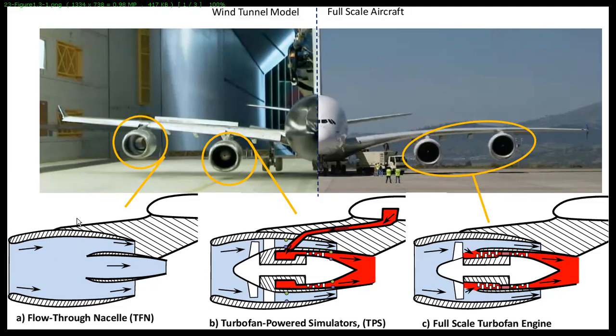And to compensate for this instability, they put software inside. They could have increased the tail and remained stable at the same level, but they don't want to increase the tail, because an increase in tail area also increases drag, and fuel efficiency will be lower.